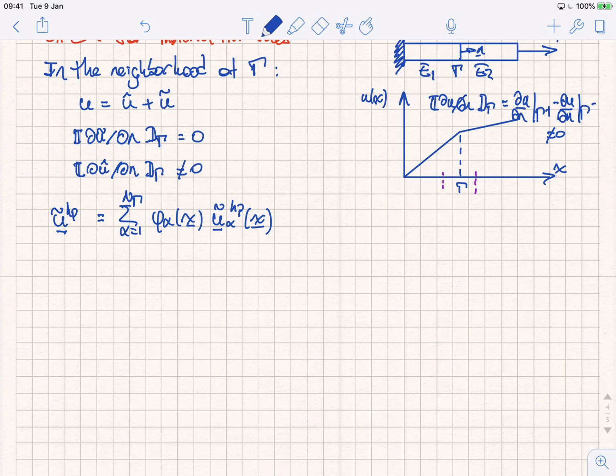If you have a finite element mesh that has, let's say, 10 nodes, and you grab the first node, well, the first node is associated with the first shape function, that is phi1. Let's say that phi1 is in a corner in a two-dimensional domain, and that corner is connected to two triangular elements, for example. That means that my support for that node 1, x1, is basically those two elements. Now, if I take some function u tilde to represent some behavior that I want in that cloud, I can localize that behavior by multiplying that with the shape function phi1. Everyone is following me? Yeah?